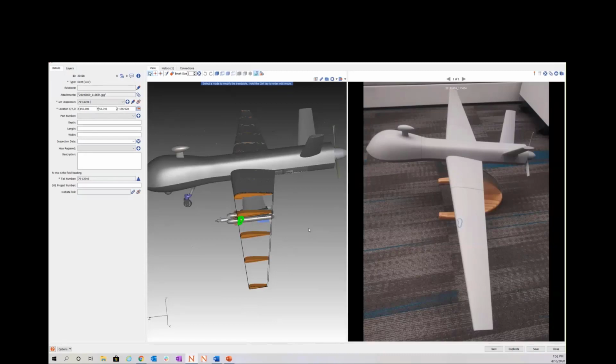There's a couple of things you can do with a setup. So if you have some type of a jig where you take the picture exactly the same every time, you can even get it to be automated. Okay. But let's say you don't want to quite go that far. Let's say you typically have someone take a picture in, on average, some type of an orientation. What you can do is you can save that typical orientation into NLign. And so as it does some initial guessing on how to align and map the picture to the model, it will be faster and more accurate.